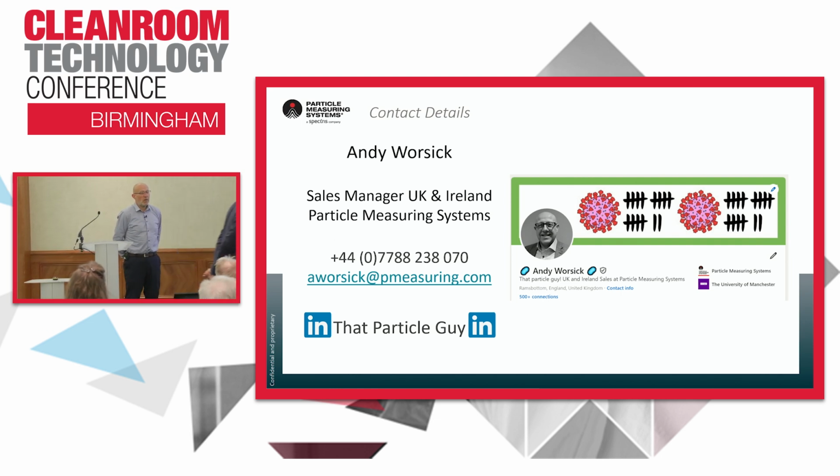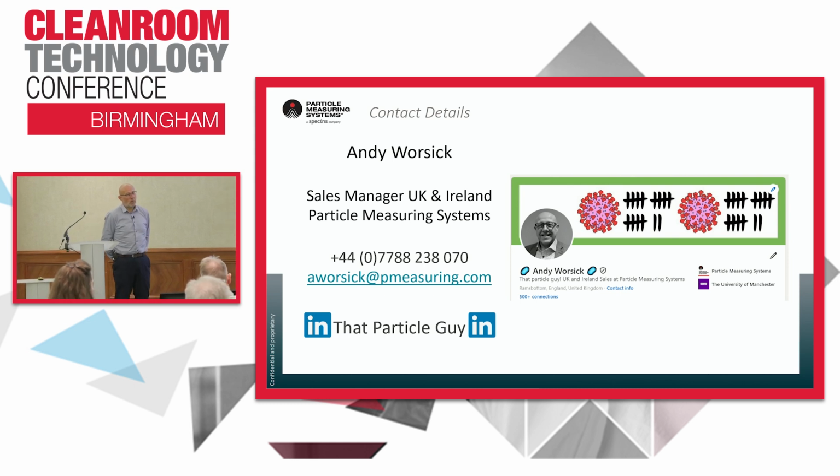This is a question, Andy and Hasim, you might want to jump in here. One of the concerns I always have, at least in life science, is when people monitor a cabinet, they'll set up an isokinetic probe for continuous monitoring of a BSC or a flow hood, and the probes are always facing upwards towards the HEPA filter. Back when I worked in electronics, we would never do that. We would always have the probe facing towards the risk, because we wanted to monitor where the contamination was coming from.